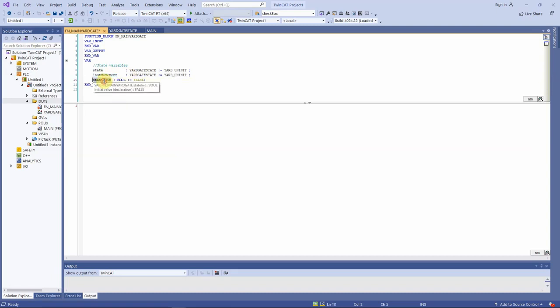When we use the gate, it changes its state. When it is going to a new state, we change the state variable to the new one. In the next PLC cycle, we will use the new state. We might need to do single-time initialization for that state. We shall tackle that with the state init variable. After doing the initialization, we change it to true, so in the next cycle it will not execute the initialization part anymore. So state init is a helper variable.